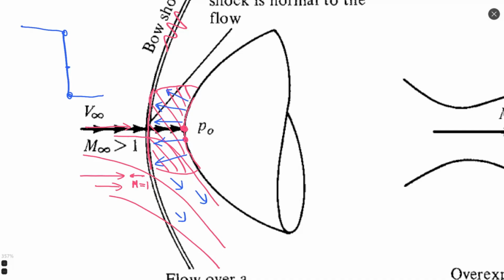That is absolutely not correct, because we never have Mach 1 inside the shock wave, even though it's decelerating from more than 1 to less than 1. Mach 1 does not exist inside the shock wave. We never see it. So I think it's not appropriate to use average values on the shock wave.